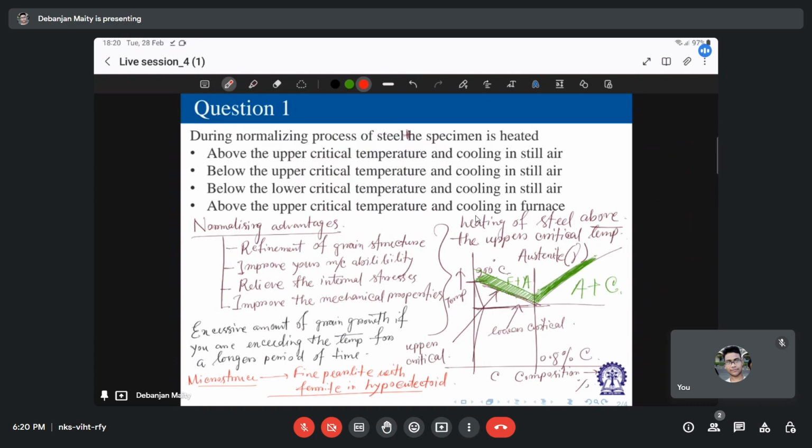to refine the grain size but also to dissolve the networks of carbides that may have been developed during forging or rolling or whatever working operation you are doing, and in some instances during case carburizing also. So that is another heat treatment process where the carbides can be dissolved. At room temperature, the newly formed structure consists of fine-grained pearlite with cementite for this hypereutectoid steel. Correct. And this normalized structure is more suitable for spheroidizing treatment to obtain good machinability.